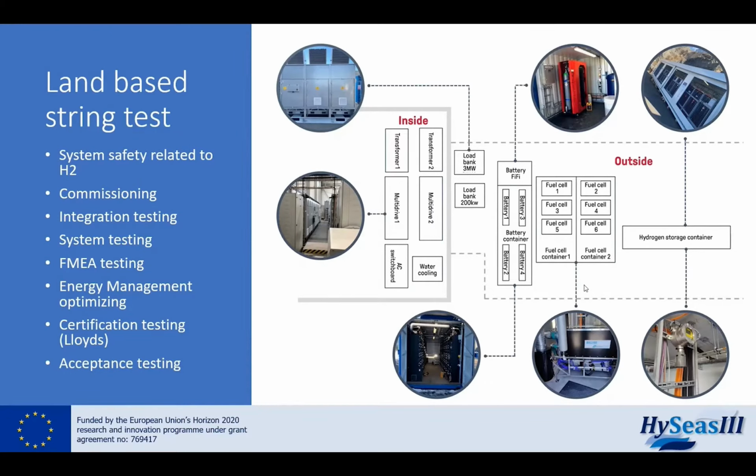Not having a yard or vessel owner hanging over your shoulder and pushing for sheet drives gives us a much better time to do the integration and testing in a controlled environment. In this controlled environment, we can run the same sailing profiles many times with different energy management strategies. Logging the data from this test, we can optimize the usage of fuel cell and battery to maximize the efficiency and also the fuel cell lifetime.